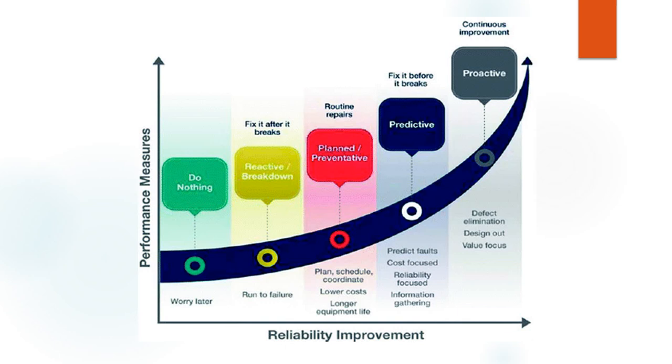For example, if I'm talking about the lube oil pump, which delivers oil to the gas turbine, is it critical or not? Of course, it's critical, right? But if this pump has a redundant one, is this pump considered to have the same criticality or less?